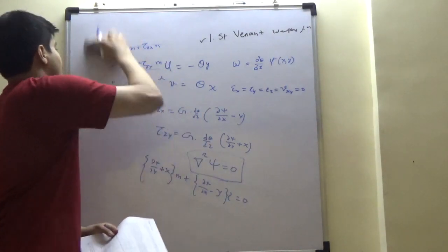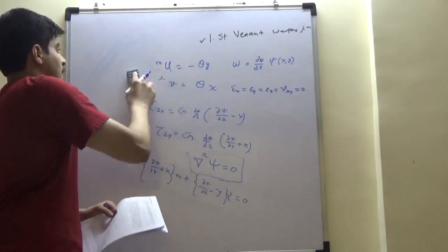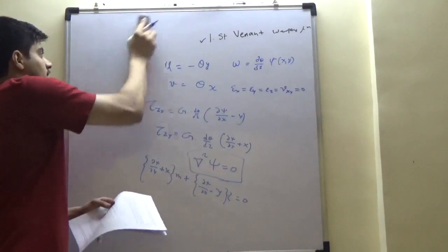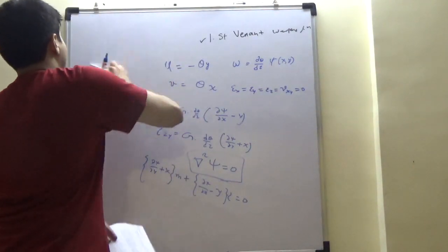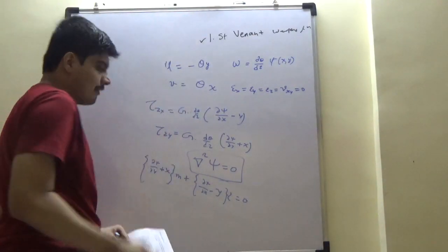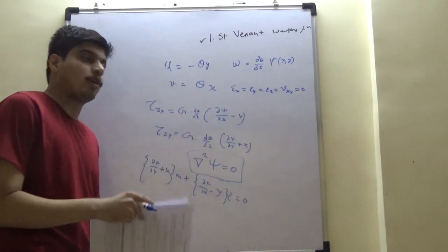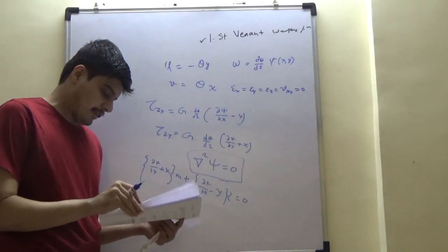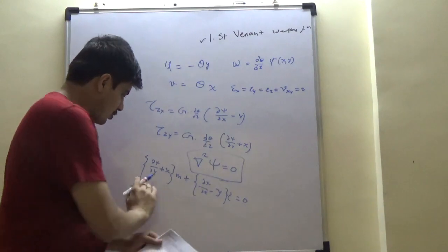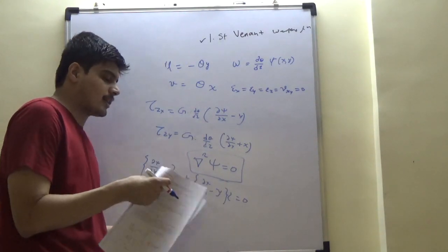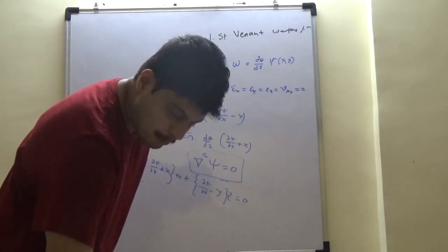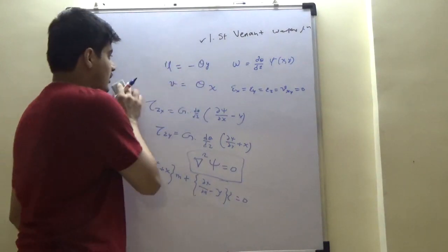I am using the second equation of equilibrium from here, in addition to, of course, the equation which we looked at, which is this, correct? So effectively I am saying that these equilibrium equations provide me a similar analogy as the Prandtl stress function. Now you can show easily that this also satisfies your stress, but that is not a part of any GATE or standard examinations.